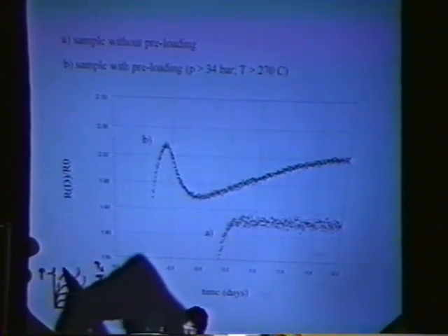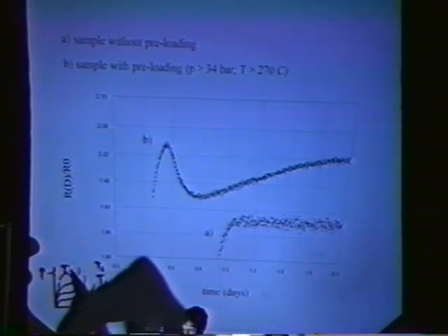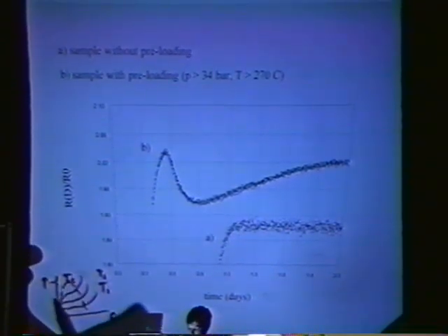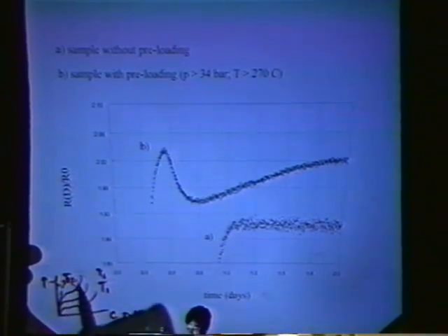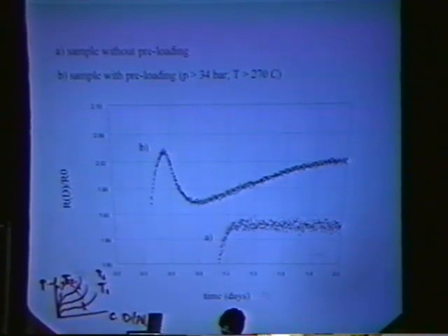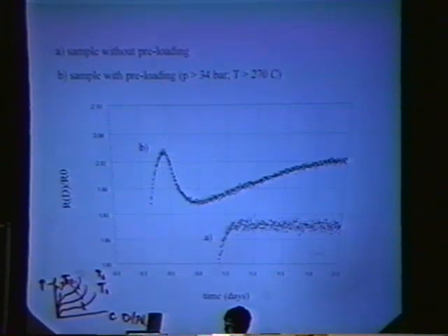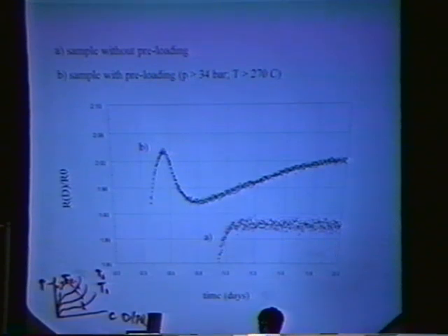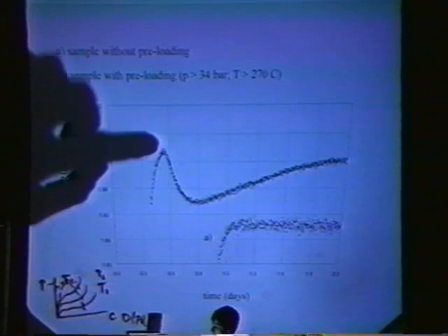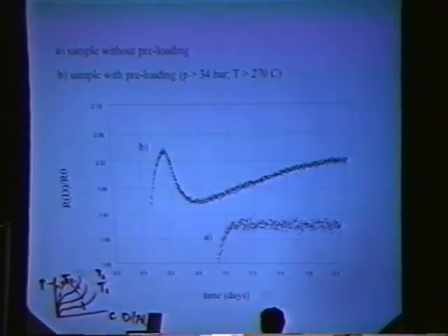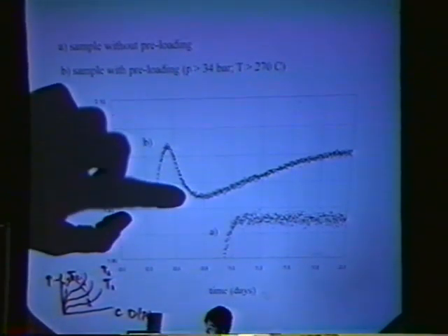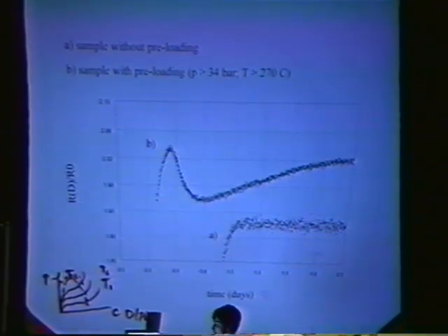You can go over the critical point with a trajectory like this one, and then you obtain again the beta minimum value, because it's a stable point, but you avoid the growth of the beta phase inside the alpha phase, because beta phase grows like bubbles inside the lattice. So in this case, we obtain a very different loading behavior, and at the end, a higher loading ratio.